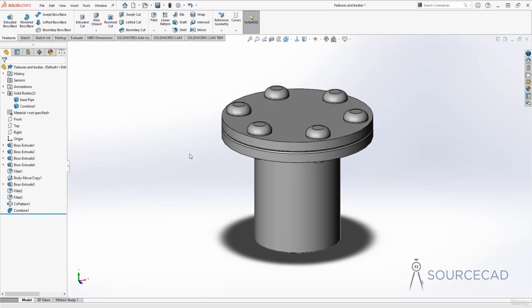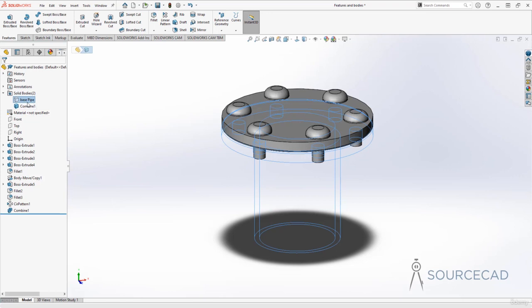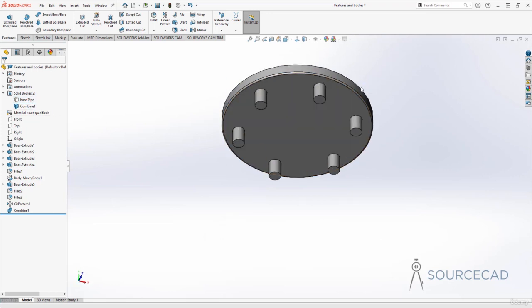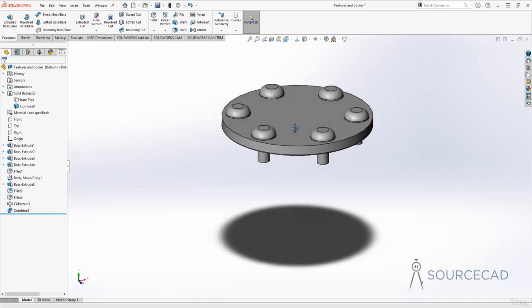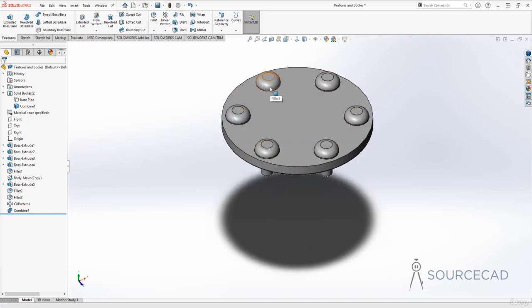And just for the sake of simplicity, let me hide the base plate so that you can see this thing clearly. So I'll hide the base plate and here we are. So this is now one single body. So that's how you can combine the bodies once you are done making modifications on separate features. Now here in this case, these rivets actually are made with just one main rivet. Now if you later decided to just change something in the main rivet and you just want the same changes to propagate to all the other copies, then you can do so very easily simply by modifying the main